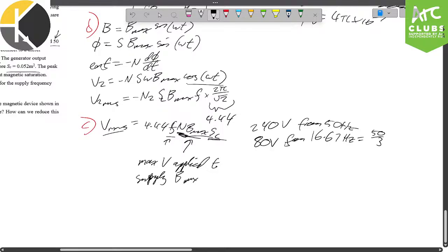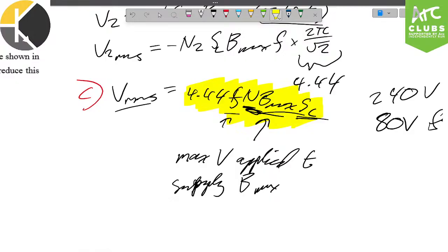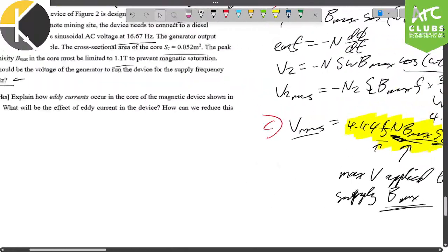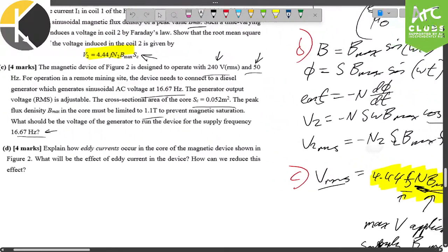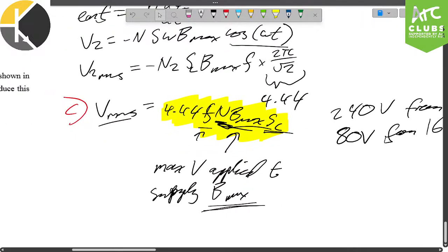It's very goofy, and it's very much understanding that, okay, are we using the same formula? This is something that is relating just transformers in general. So I think the main difficulty, main thought process behind this question is to understand that, okay, B max is being kept the same because we're supplying some manner of voltage, however great, depending on whatever N1 is from the other side of this machine, to saturate the core, okay?